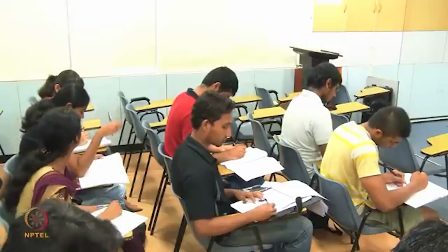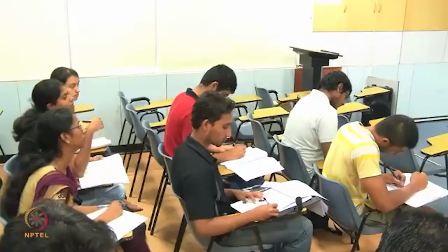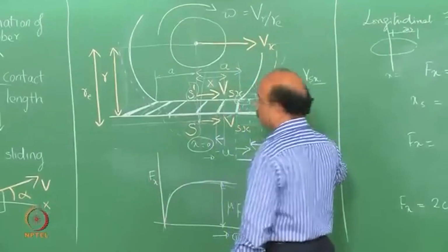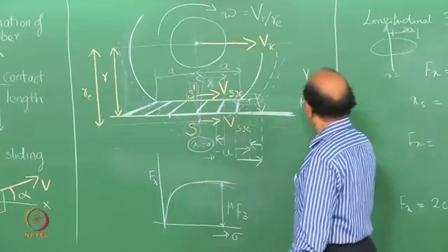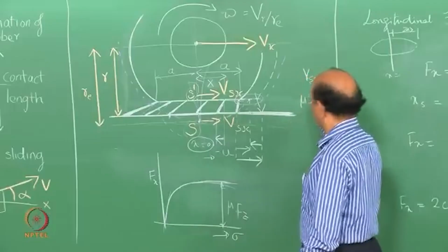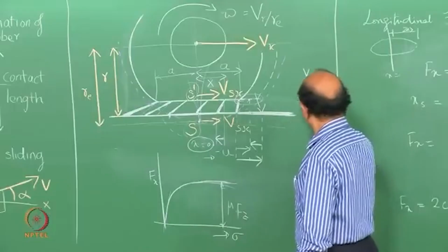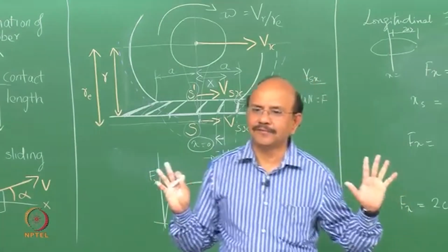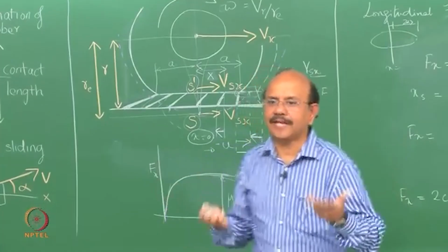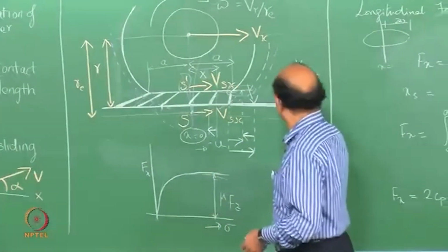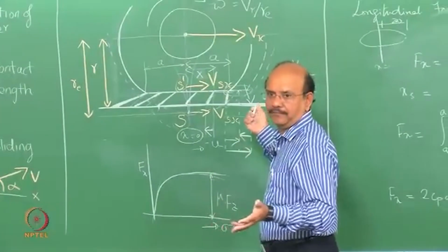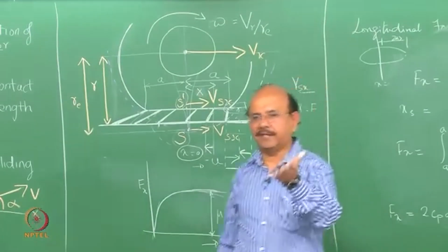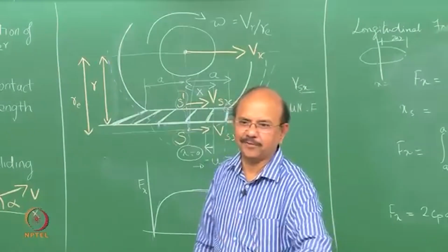Qz is the normal. See, what I am using is nothing but mu into the normal force, very well known. That's all I am using. Only thing is I am using it per unit length. Right. So this is actually an inequality. This is not an equality. So whenever F is greater, it won't slide. That's all. Whenever it's equal, it will slide.